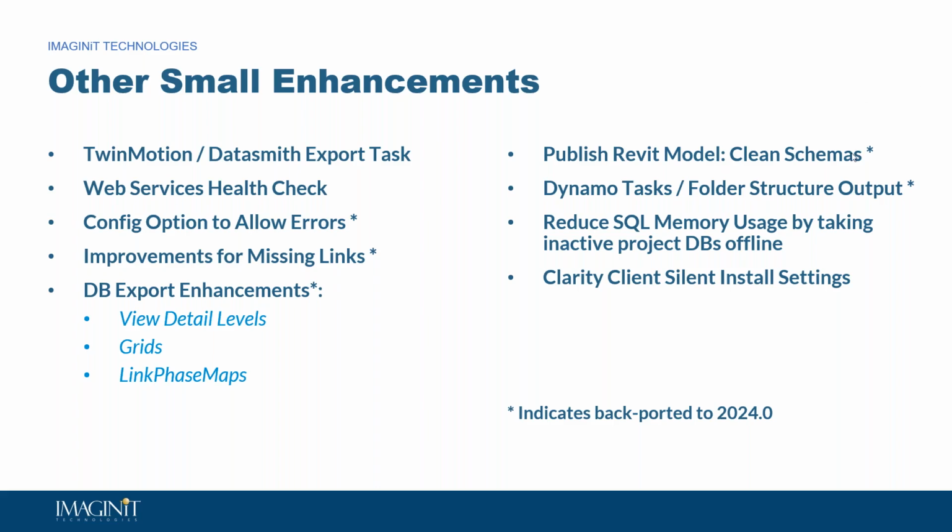There are some restrictions and some quirks to the way that works, but we have built in clean schemas as an option into Publish Revit Model, as well as, I forgot that we did this, but based on some customer feedback during the beta process, we added it as an option to our audit, compact, and purge task. So you can also clean schemas while you're doing model maintenance.